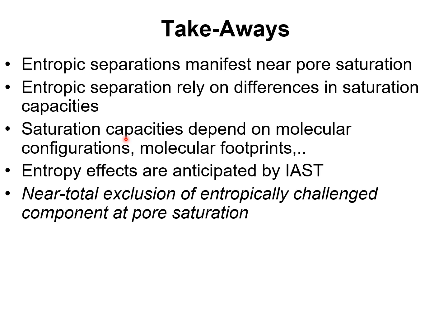The saturation capacities depend on molecular configurations, molecular footprints, molecular sizes, etc. It's important to note that the entropy effects are anticipated by the ideal adsorbed solution theory. And one important characteristic of entropic separations is that we have near total exclusion of the entropically challenged component at pore saturation.